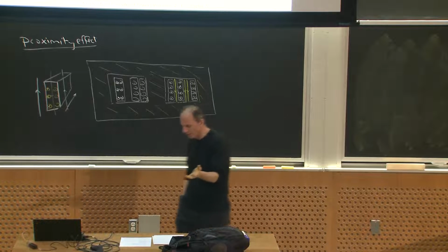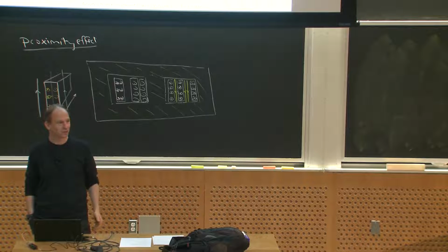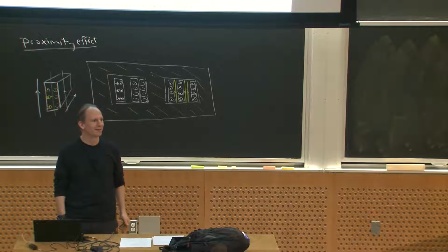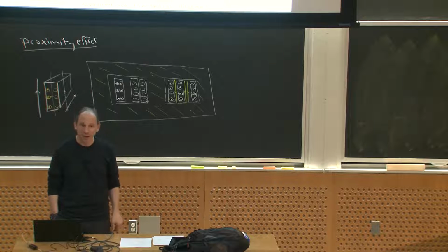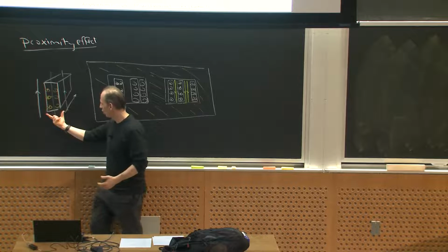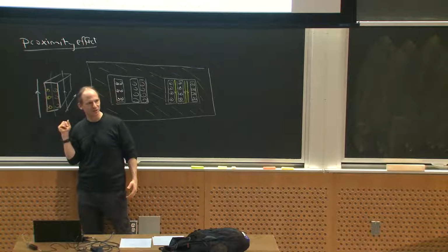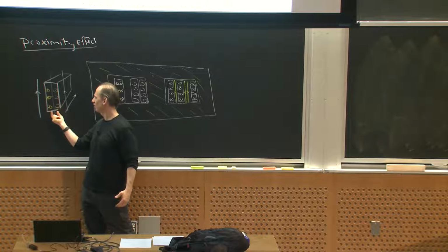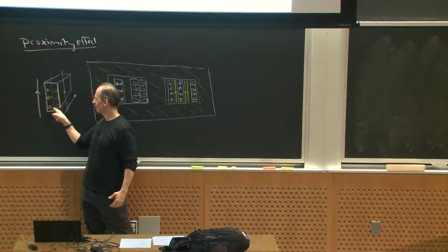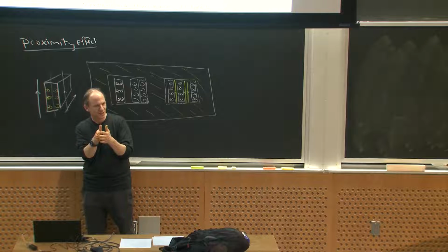So that's just sort of a warning, because you can get into this weird situation, I've been there, where you think, oh, my conduction loss is too high, I'm measuring it, I've got too much resistance, so what's my natural inclination? Put in more copper, use fatter wire. And you find out, you put in fatter wire and the resistance goes up, right? And the reason the resistance goes up is because, as you make this conductor wider, there's more room for the eddy currents to circulate because of proximity effect. If you make the conductor thinner, this current going this way and this current coming back kind of overlap and cancel, and you get less proximity effect loss. So sometimes it can be better to use thinner wire instead of thicker wire to get less loss in net.